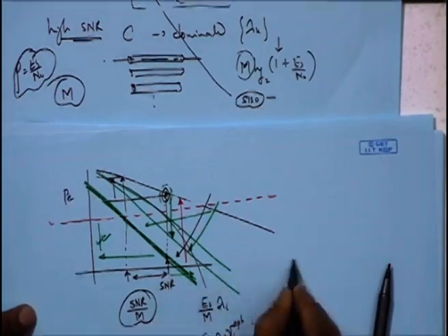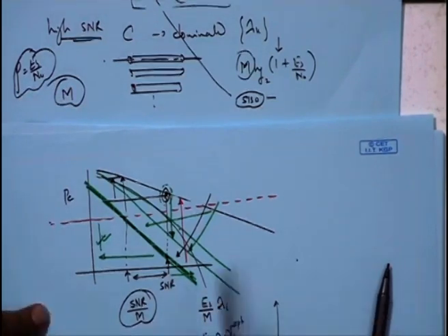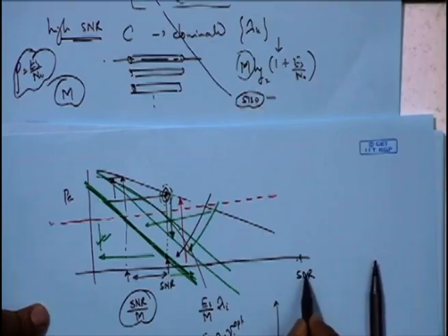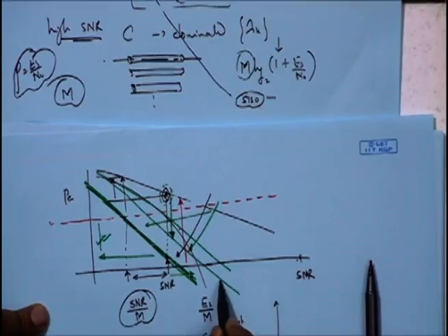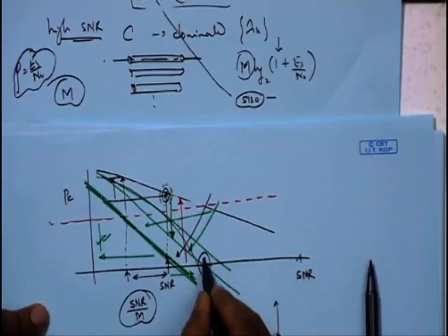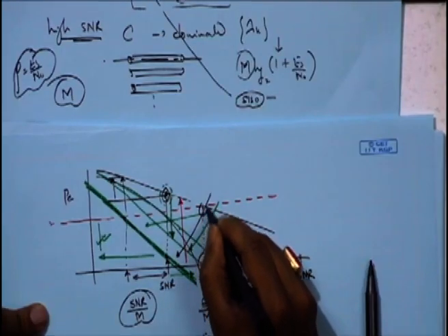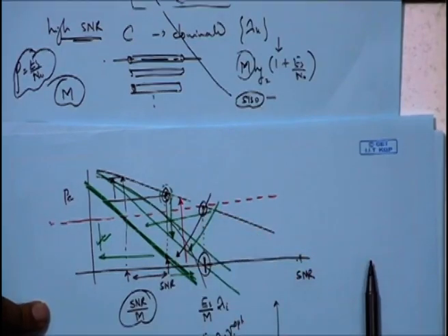Whereas if we are in the high SNR regime, that means we are somewhere here, let us say at 30 dB or 40 dB SNR, if we distribute this SNR amongst multiple channels, suppose I get the average SNRs per transmit antenna at this point, so that the error probability is just satisfied, it is below this red dashed line.